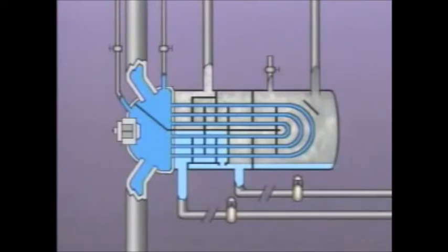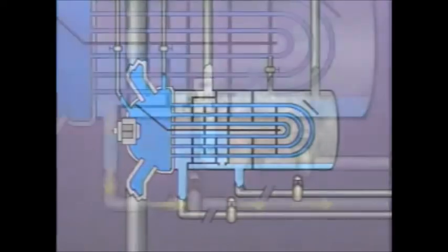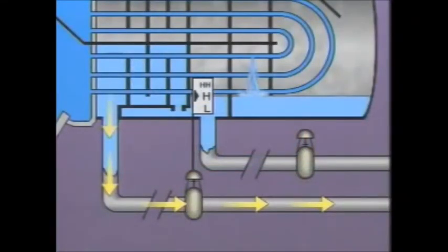Tube leaks are another common operating problem associated with closed heaters like this high-pressure feedwater heater. Even small leaks can significantly increase the volume of water in the drips, causing the lower tubes in the heater to be blanketed with feedwater. Tube leaks also make the heater's level control valve open farther than normal.